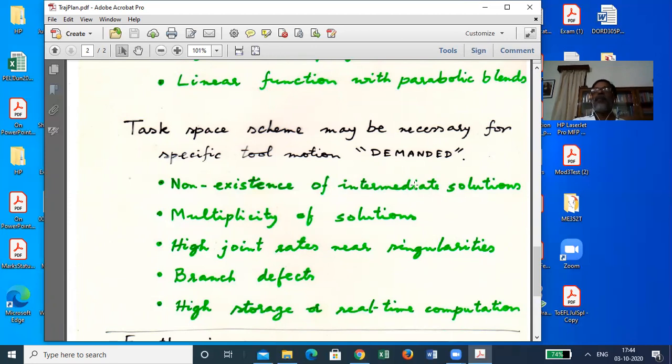In the case of joint based planning, you could have done it because you knew that this particular joint can move from minus 120 degrees to plus 140 degrees, or 0 to 360, a full circle. Within whatever the range of that particular joint is, you could say that whatever motion is in this joint, we accept it.